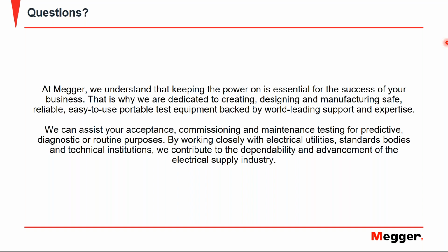Okay, thank you for this question. First we have to understand that whenever we're taking partial discharge measurements, we have to pass a high voltage source through the cable to get to the point where we're producing partial discharge to be able to measure it. So for that very reason, yes, there's dangerous touch potential at each end of the cable whenever we're taking these partial discharge measurements.